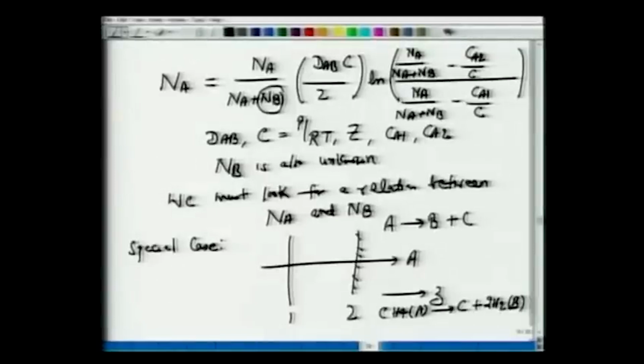So the surface is acting as a catalyst. In other words, there are no homogeneous reactions inside these two planes. So RA is still 0, but when A reaches plane 2, it gets decomposed by catalytic reactions into carbon and hydrogen, which diffuse in the opposite direction.